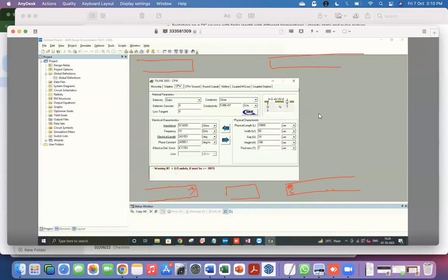If you sort of ignore the center conductor of the CPW, then if these two conductors are allowed to develop a potential difference, then that's exactly what the slot line mode is, right? Because here, in order for the wave to propagate, there has to be some potential difference across these two conductors, right? Obviously, it'll happen at the edge, and then you won't have much penetration inside. So you can have the same thing happen over here. If you develop a delta V on this, that's actually another propagation mode.